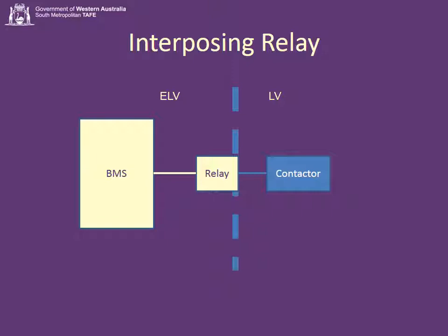However, when the contactor opens and closes, it sends a 2000 volt spike down the line. The only thing that's going to get blown up is a $15 relay, rather than a $3,000 BMS system. So it's another thing to go wrong, but it's effectively a fuse.